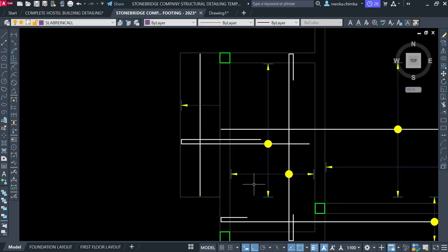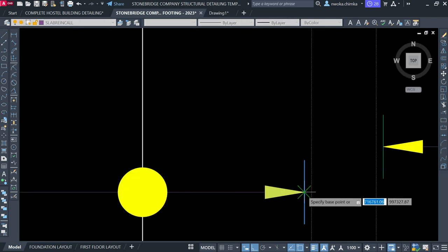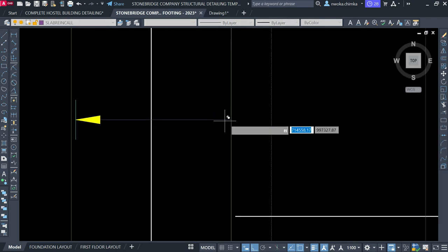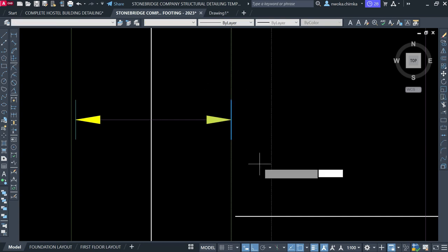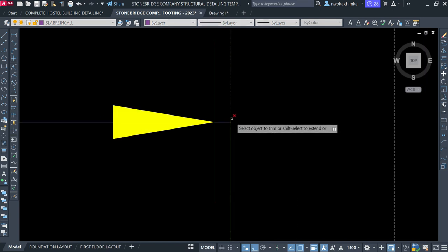And then come again for this other direction also, and then copy this. C or CP can work, and then go all the way down here and then keep this here. Okay, and then come here, select it entirely, and then move by 25, come here 25, that's fine, TR, okay, enter, and then come here.